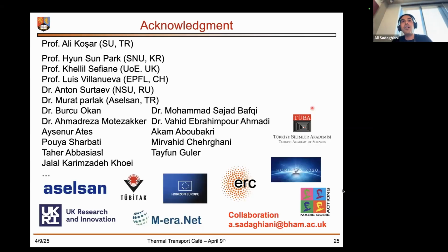So the presence of non-condensable gas in mixed wettability, especially the effect of a superhydrophobic spot on the nucleation on non-degassed water, was very evident.